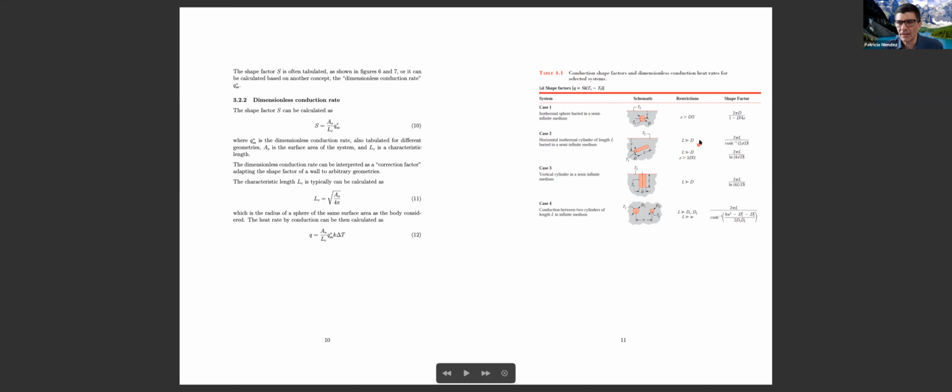So length much bigger than diameter. That's a check for either of the solutions. Now it says, how deep is it? For any depth, we have this formula here. But if the depth is bigger than 3/2 diameters, and the depth we said was 2 meters and the diameter was 70 centimeters, give or take, so we are deeper than what it says here, we can use this other formula that uses a log instead of a reciprocal hyperbolic cosine.